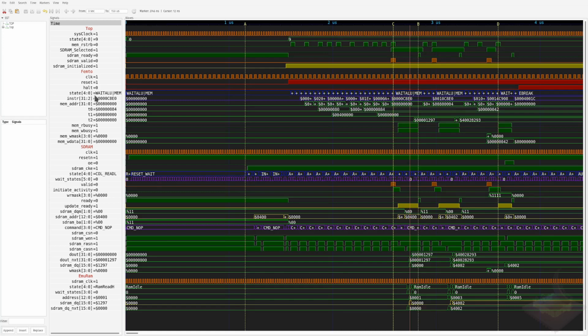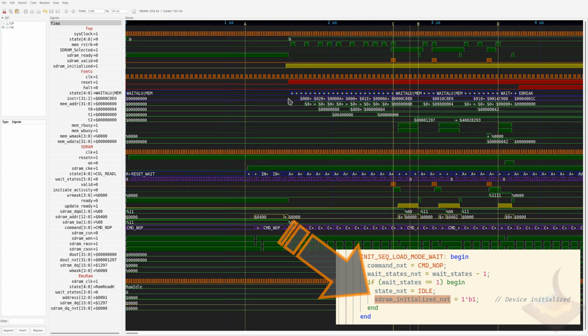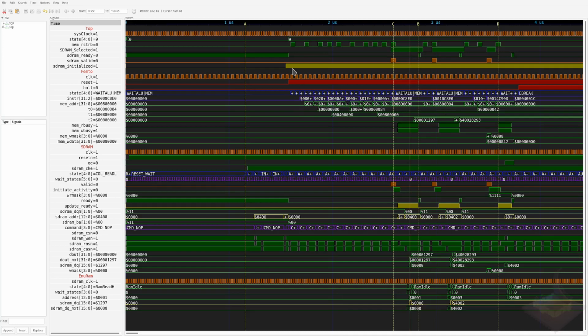We expect the Femto to start running things as soon as the SDRAM is initialized. So it stays low, and when it's initialized it goes high. And it looks like the Femto is seeing activity. It's beginning to do its thing right about here where it uninitialized. So far things look pretty good. That's excellent. And when it hits the EBREAK, it finishes. Now I expected this section to run pretty well. We've obviously been using the Femto, so that's all looking good.